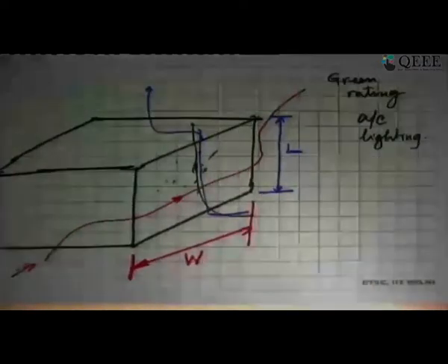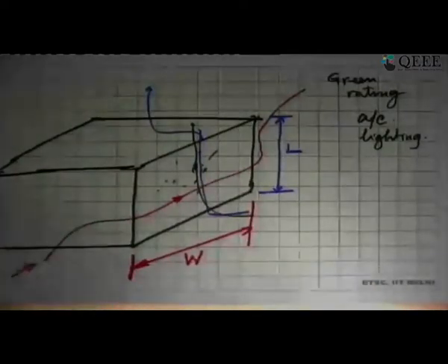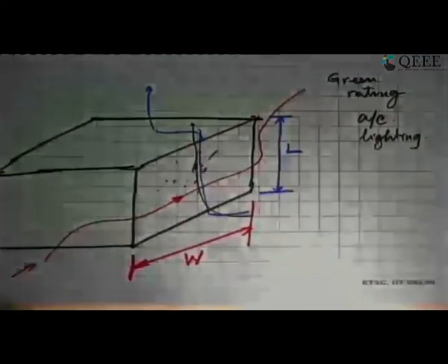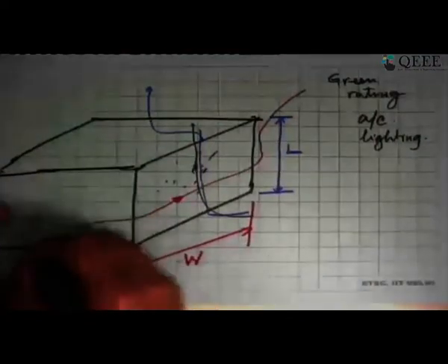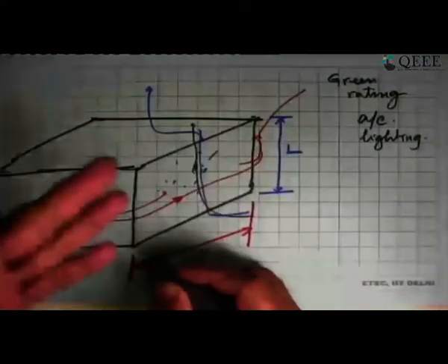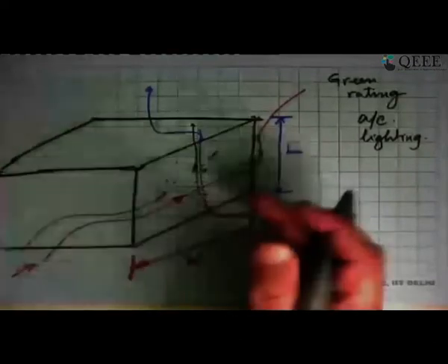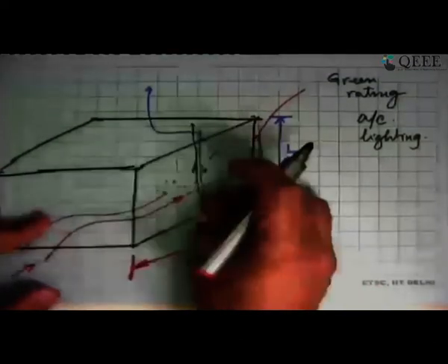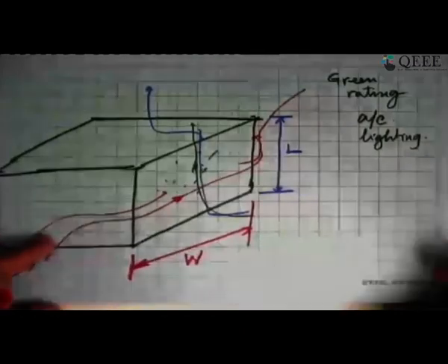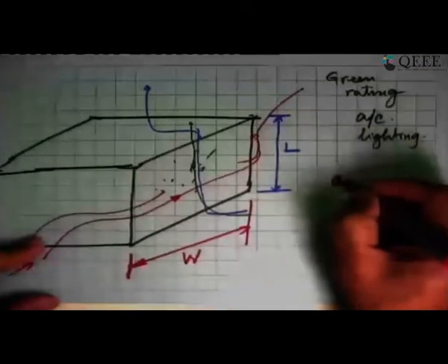The second thing that will happen is, even on the forced convection analysis of this problem, we say that I will take this wall as a flat plate with a flow parallel to this plate. But in reality, that is not happening because this flow is coming in and bending around this thing, coming here and then again bending around over there. So it's not strictly a flat plate, but assuming it to be a flat plate and letting the boundary layer grow from here is the simplest assumption we can make, and we get some order of magnitude of this answer. So those are the type of geometrical approximations that we do.